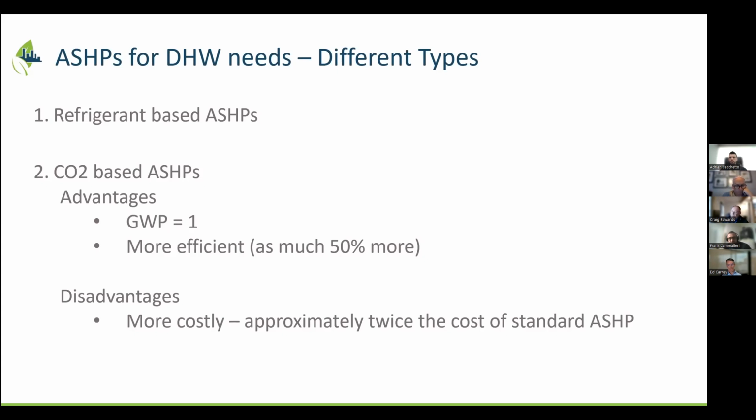Yeah, well, the reason why we've tried out our first CO2 heat pump was because the technology became available. It didn't really used to be available until a few years ago, and the product that we used at our Kitsilano outdoor pool just recently became available, so we used that. But the main driver was because the refrigerant is low in global warming potential, and we put in a ton of heat pumps with 410A and 134A, and our experience is that we do get leaks in those refrigeration systems.